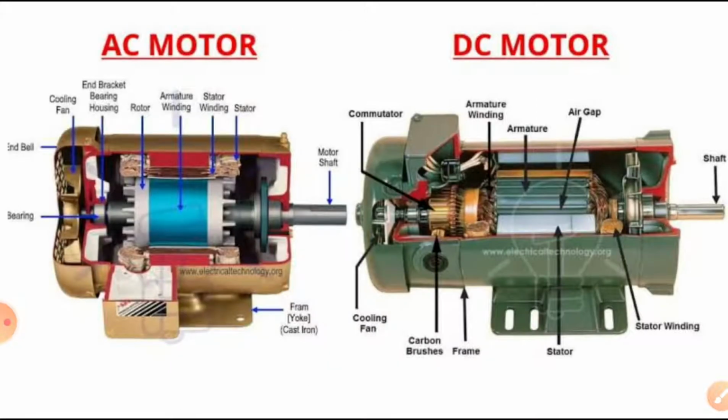Now, let us compare AC motors and DC motors. Already we have seen, AC motors are user friendly, whereas the DC motors have the commutator and brushes. Due to this, speed control is only through the armature control. At the same time, speed is also limited. Otherwise, a spark may occur on the armature commutator segments. Whereas in AC motors, no problem.